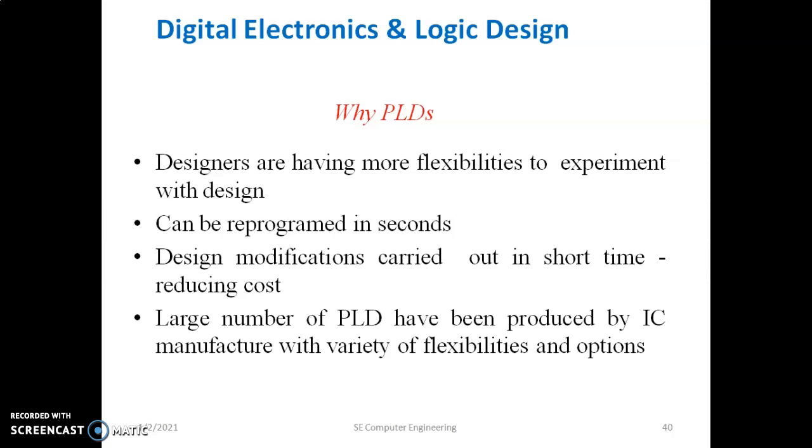Why are we using PLDs? Because designers have more flexibility to experiment with the design. It can be reprogrammed in seconds, and design modifications are carried out in a short period of time. That's why a large number of PLDs have been produced by IC manufacturers with a variety of flexibility and options.